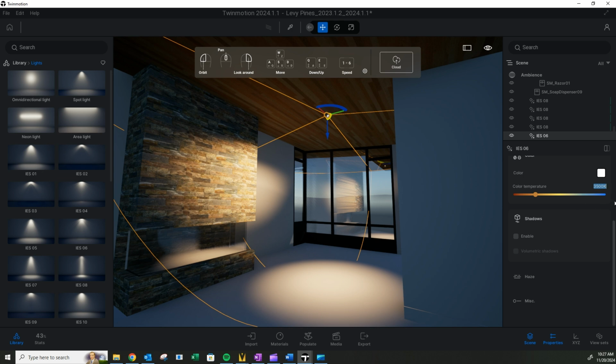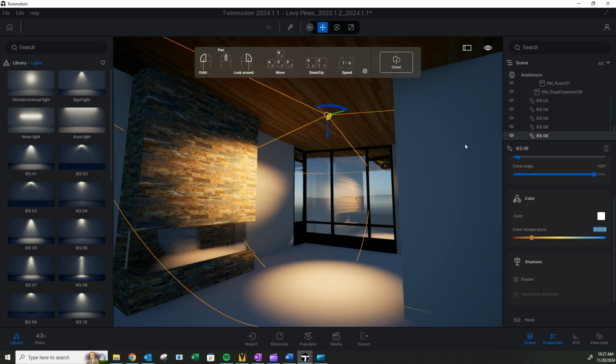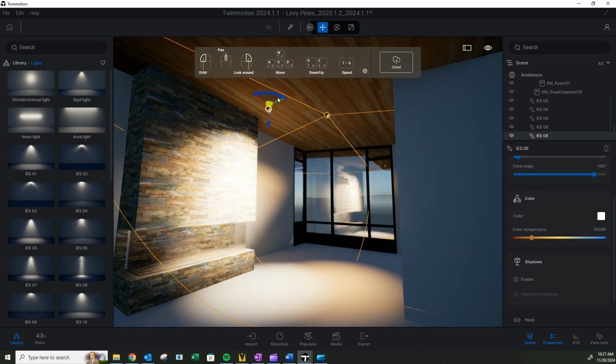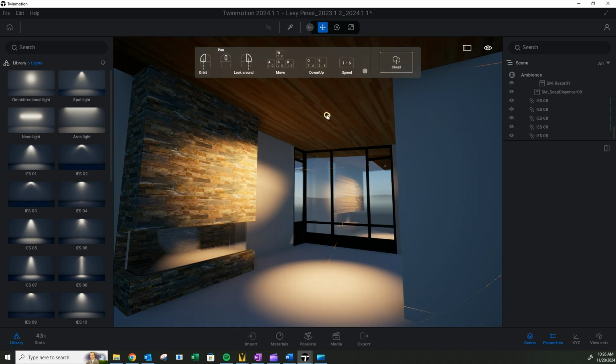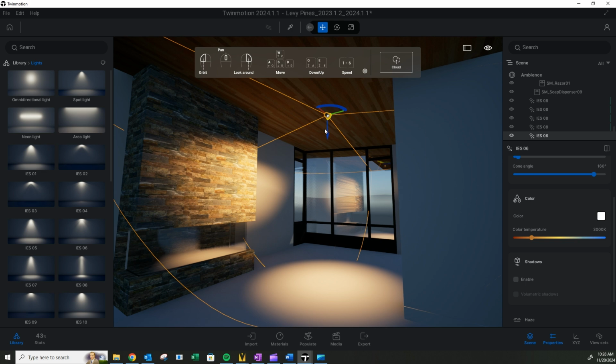In residential, sometimes we want 3500K or 3000K, to make it feel warm. There are different lights. A good light will have different optics that you can choose when you build the part number out. And the purpose of that is based on the ceiling height. So if it's lower ceilings, you usually want a wider flood.